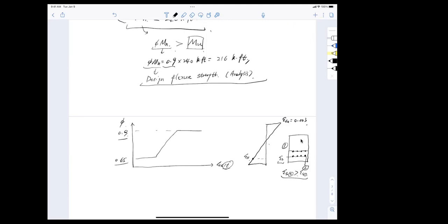But let me see. Jacob Shantz. Jacob. Yes. Hey, how are you doing, sir? I'm doing good. How are you? Not too bad. So now Danny has answered the question correctly. So the lower layer has a larger strain. My question is, if layer 2 has yielded, so that means epsilon s2 is bigger than epsilon y, is my layer 1 yielding? Not necessarily. So unknown, right? Uncertain. Great.